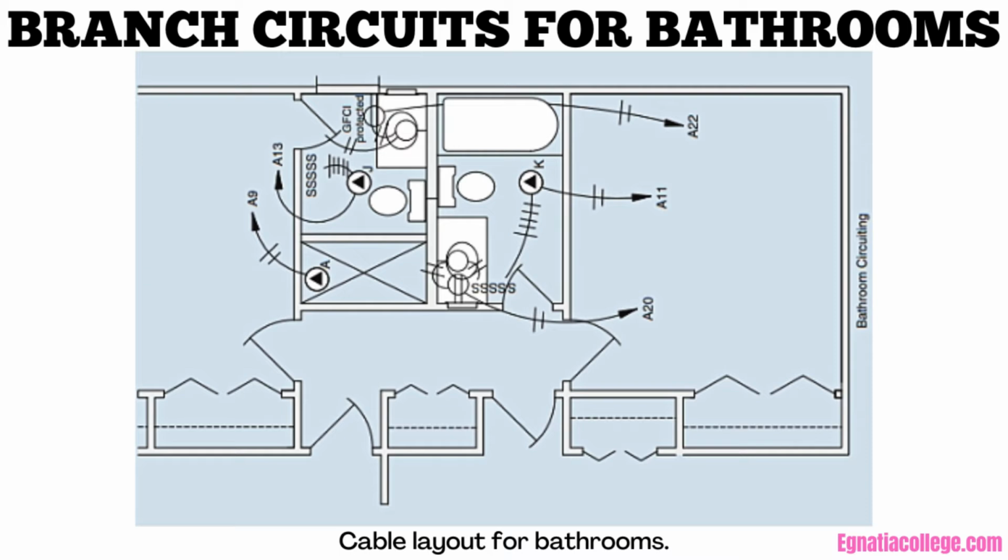There must be enough circuits to operate all of the equipment without the possibility of overloading circuits. It is also important to correctly locate luminaires to achieve proper lighting. The vanity lighting for the two bathrooms is provided from the circuit that supplies the ground fault circuit interrupter, GFCI, protected receptacle in each bathroom, A20 and A22.